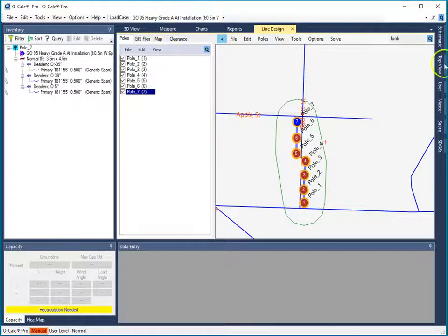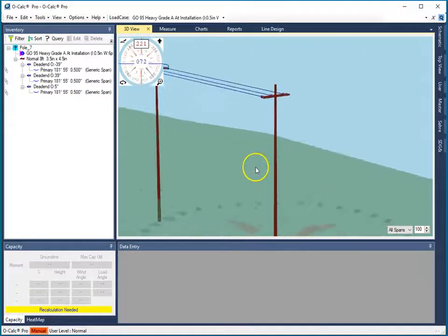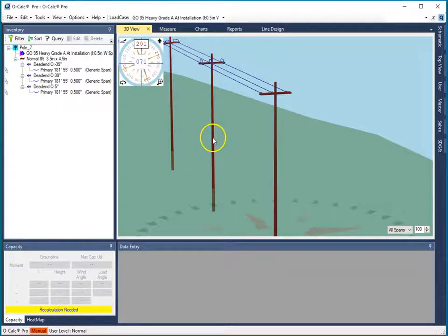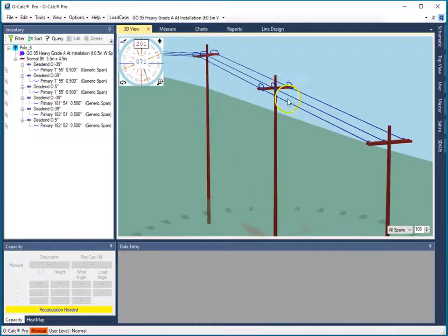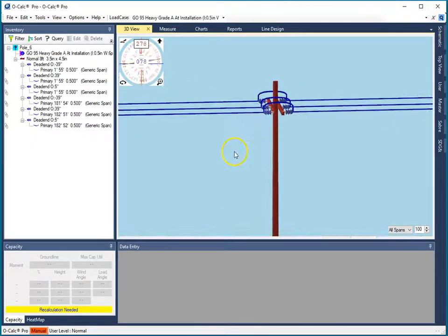And just as quickly as that, the system went and made all those PPLX files and hooked them all together. You'll notice, because it understood that that pole was using dead end insulators, that it was supposed to use the new jumper feature of O-Calc 6, and rather than taking two spans and putting them on a single insulator, it put a matching dead end insulator on the other side of the double arm and put a jumper to keep connectivity. And so just like we saw earlier, the connectivity is maintained, the edit will go right down the line.